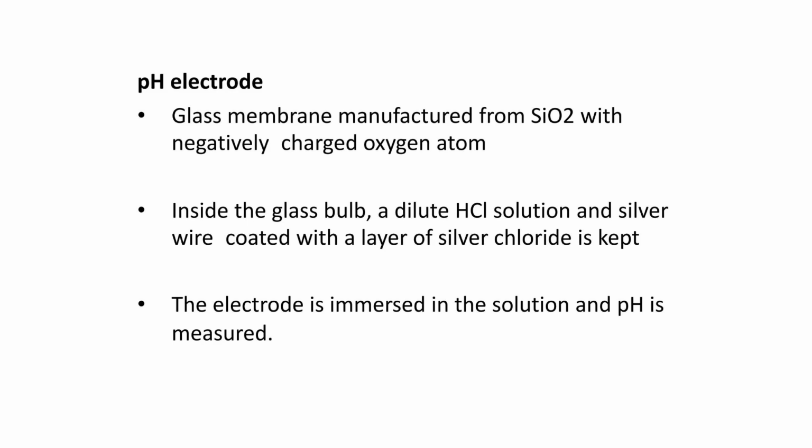The exact physical assembly of this pH glass electrode is manufactured from a silicon dioxide network, characterized by negatively charged oxygen atoms. When the entire electrode assembly is immersed into the liquid sample, there will be an electrical potential across the glass bulb, which allows us to read out the pH value directly through high impedance data acquisition measurements.